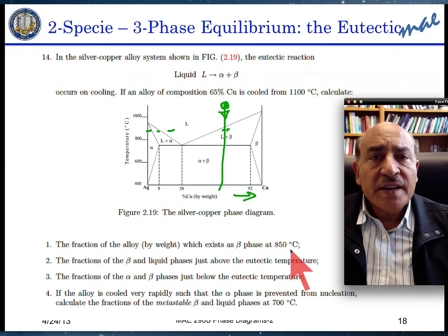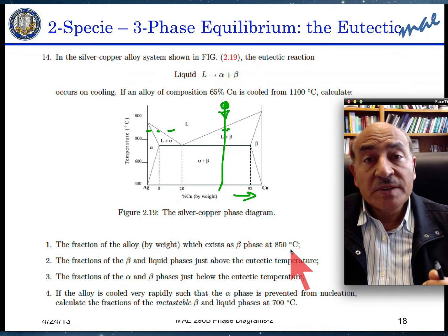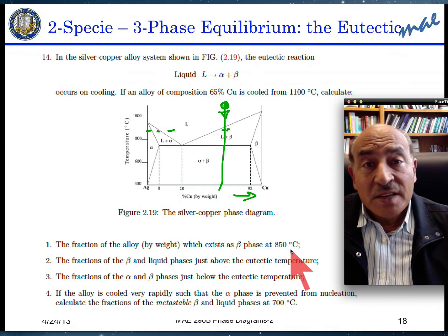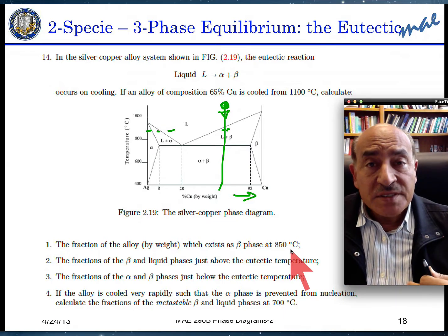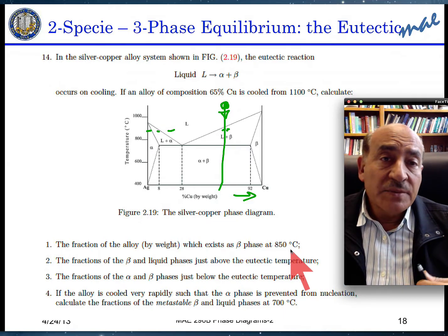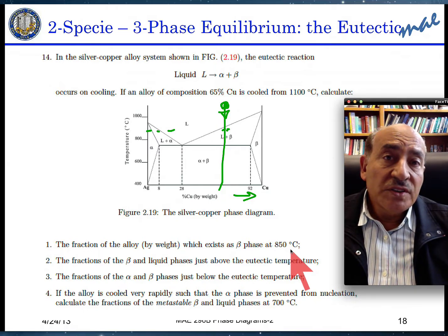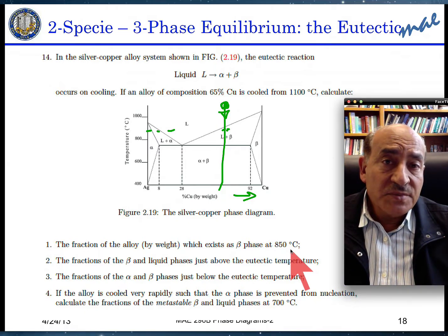In this case, we can obtain the concentrations for the equilibrium directly from the phase diagram, since the phase diagram represents the boundaries that we found from the solutions obtained from the Gibbs free energy. So the phase diagrams will be very useful by themselves just to determine these concentrations immediately.